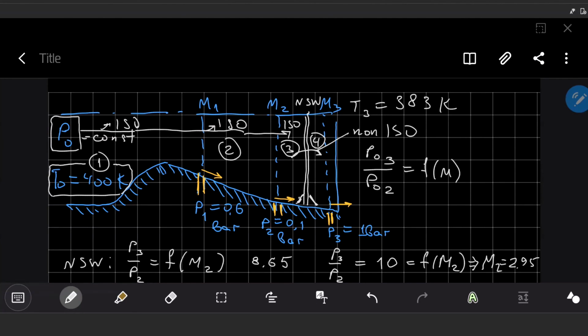What you need to do is specify other parameters which we considered constant before, like gamma or Cp, Cv, R, and make them functions of temperature. So the equation system becomes more complex. It's a very common strategy, and it works quite well. We do not need to elaborate all the equations from the beginning. We just need to extend the equation system and not consider some constants as constants anymore. We need to consider them as functions.